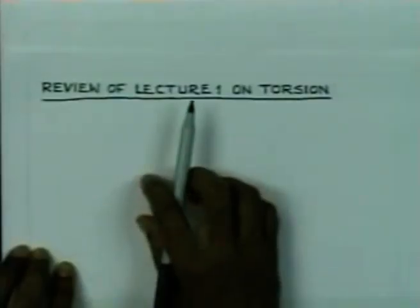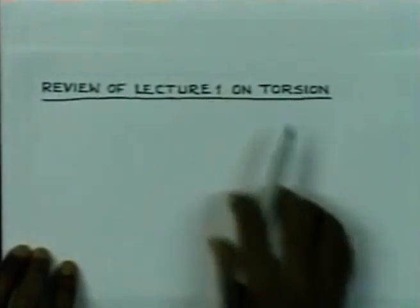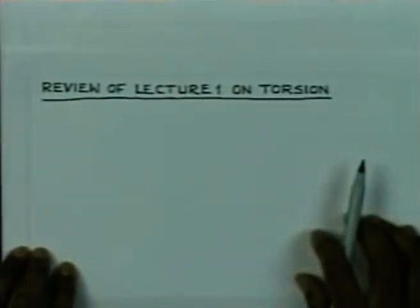Let us first review our earlier lecture, that is lecture 1 on torsion of non-circular shafts. We have noted a few things: while applying torsion, each section is going to have warping, and that warping is a solution of Laplace equation,